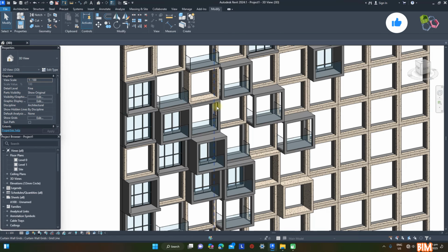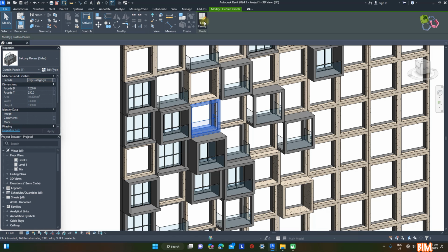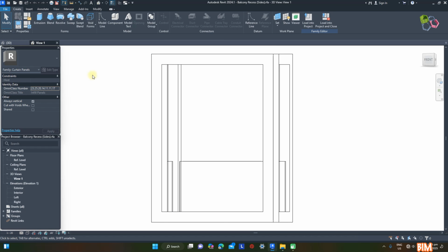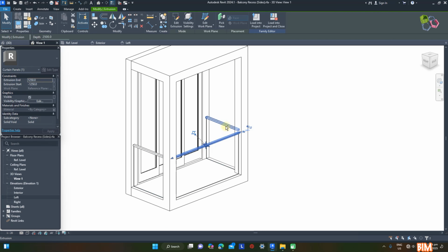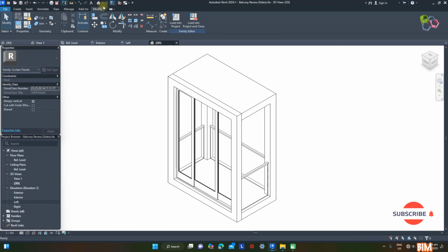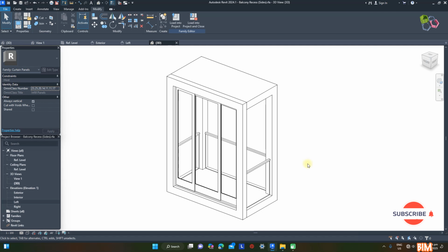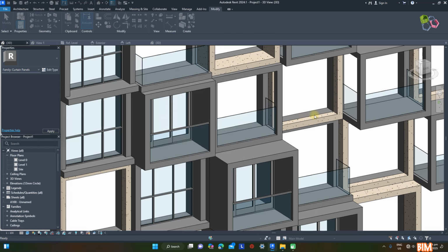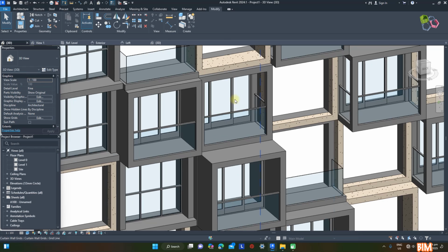I apply similar upgrades to the balcony recess, including doors and its frame, by adding reference planes named DW to determine the frame position. Add an additional 50 mm thick handrail on the glass panel. Load and overwrite the existing version to upgrade the project components.